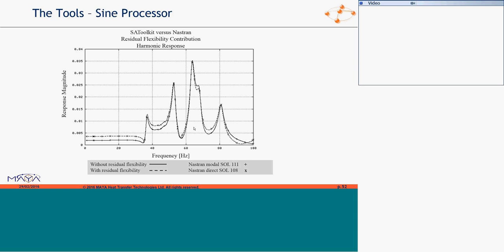The less cumulative effective mass you have, the more this is important. If you do a sine analysis and you excite off resonance, you say, well, I want to know what my response is at 20 Hertz, and the response is not equal to mass times your acceleration. You know why, right? It's the effective mass here. That make sense?